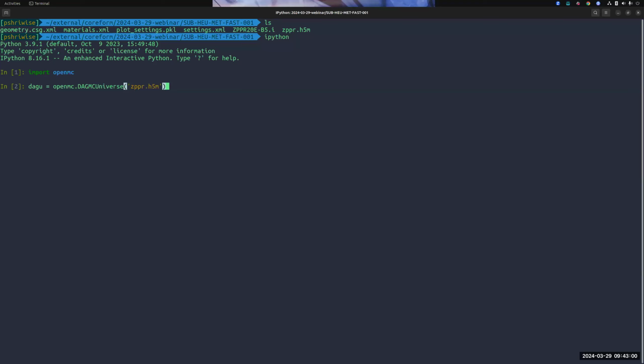So if you're familiar with CSG, you can use universes to fill other regions. So essentially I could define a box or a cylinder and then say, I would like this collection of geometry to fill that space. And that's how DAGMC geometry operates within OpenMC. What that gives us the ability to do in OpenMC is represent combined or hybrid CSG and DAGMC models. So you could have, for example, an interior core region where you have a lot of repeated geometry that's relatively simple.